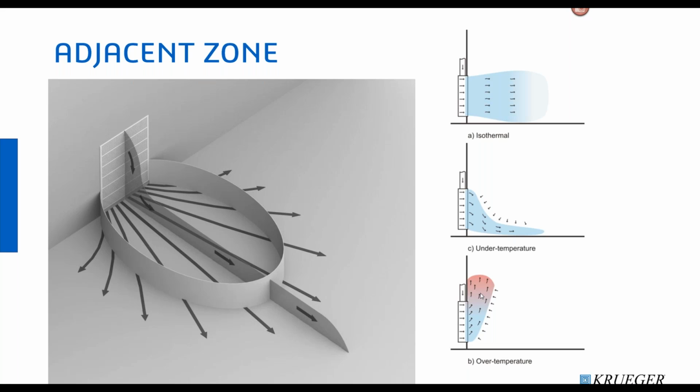On the perimeter of your building, you're still going to need to provide some type of heat solution. So that could be linear slots along the ceiling, along the glass. But on the interior zones, displacement and cooling only is still a very viable solution.